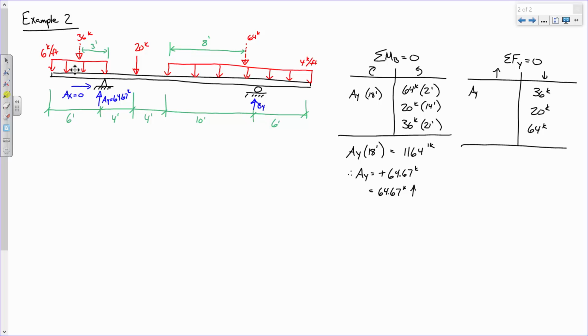Here's an easy way of explaining it. You might very well be correct if the loads are as they are. But what if this 20 kips was suddenly 80 kips? You might be wrong, okay? And really the only way to truly know is to go through and chug it out. We can't find the max moment on this intersection without BY. That's why we have to find it.